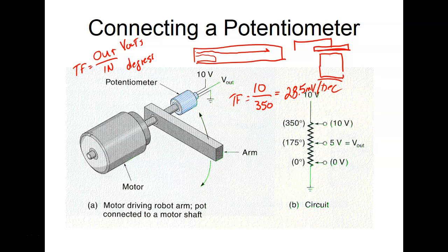That times the transfer function and display degrees on the PLC. Very, very easy. That's one advantage we get out of a programmable controller. It's a computer. So not only can it do relay logic, it can also do things that a computer could do. So it does math. So we could very easily take this voltage, this transfer function, and convert it over to degrees.